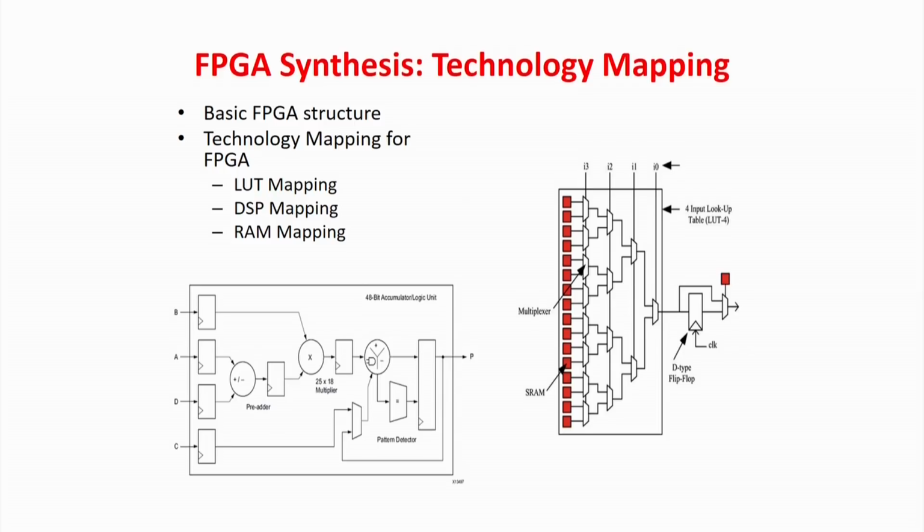Then again nowadays there are a lot of variations, so either you can fabricate your circuit in ASIC, or nowadays FPGAs are coming up. Now we have very large size FPGAs, so even processors can be implemented and validated in FPGAs. So a few modules will be dedicated to how you can have an optimized design if you have an FPGA in place, because FPGA is not a gate level block. There are LUTs and ready-made blocks like digital signal processing blocks and RAMs; some dedicated blocks are available. So say that I require a multiplier, you need not synthesize the multiplier, multipliers will be available. You have some digital signal processing blocks already available, so you can directly map to them. Given those fixed blocks, how can the other parts be optimized?